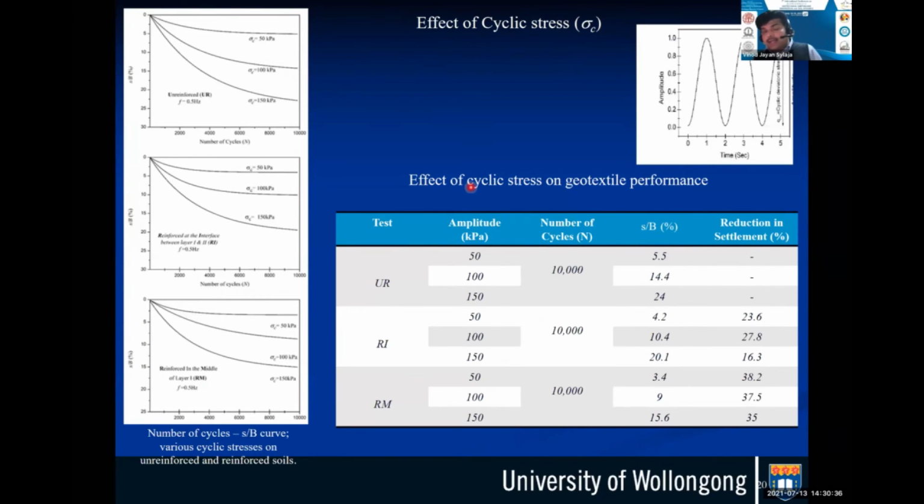We then extended that model, very similar to layer 1, with the 2-layer system, which we have calibrated in the monotonic condition, to look at the effect of the amplitude of a cyclic stress and frequency on the performance of the Coir Geotextile reinforced soil. We have used the same kind of amplitude here, and you can see the response of the model under different amplitudes of cyclic stress.